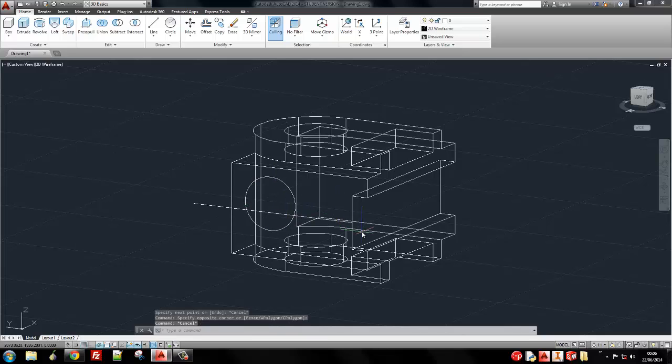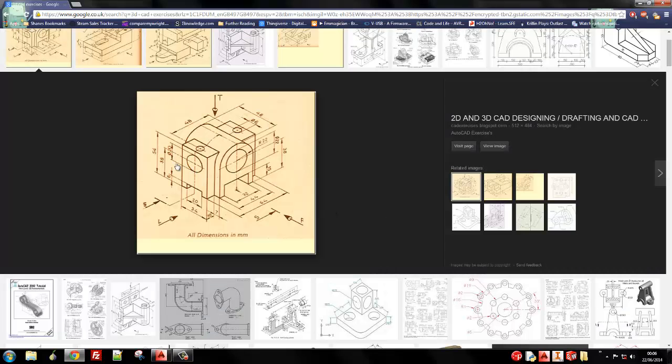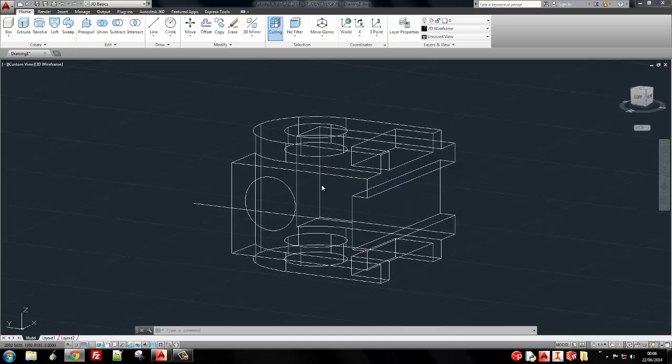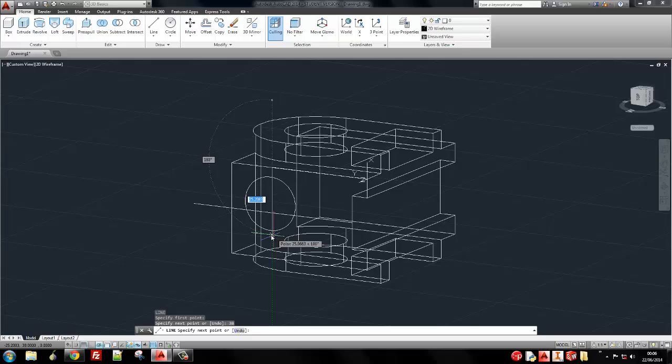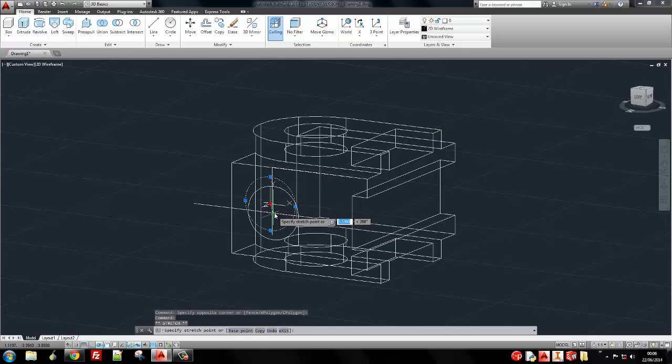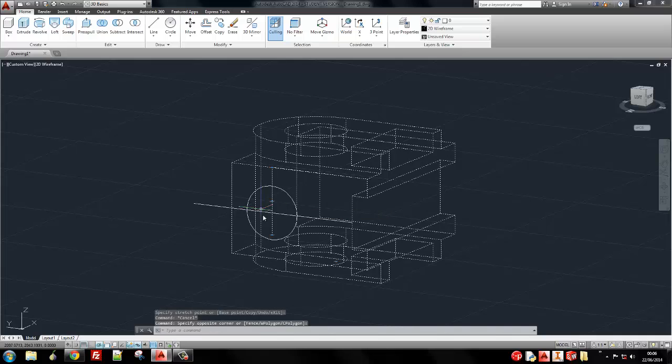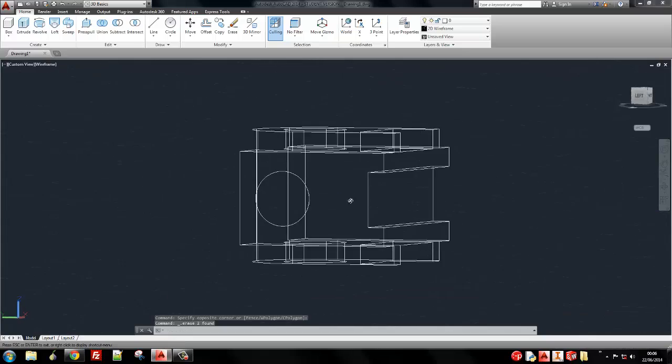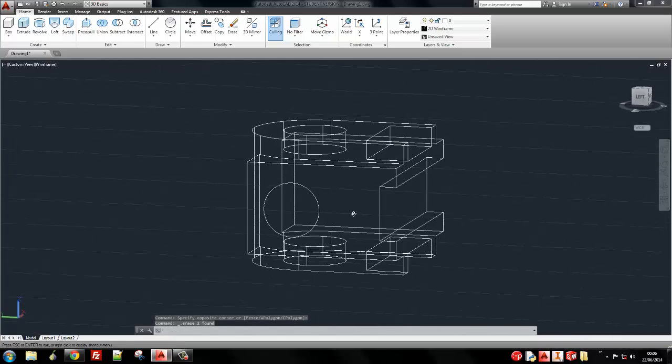And I'm going to put this on it. But before I do that, I want to know how far up this needs to be. So this needs to be 38mm up. A nice easy way to do this is go in this direction by 38 from the bottom and then put a line down. Where those two lines cross, that's the point where the center of the circle should be. So I can pick it up by its hot point, hot grip even, and you can see there's a point of intersection. There we go. Once you're happy with that, escape to unselect it. Then grab your lines and remove them. So we've got a nice centered circle where it should be. Again, I'm going to extrude that through.